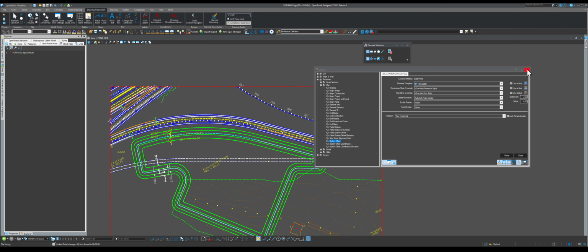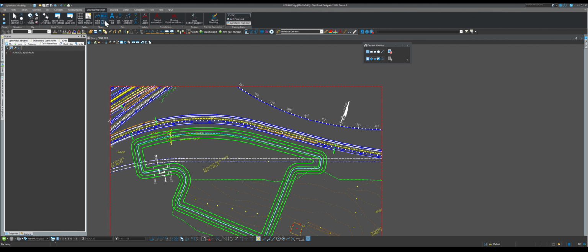We can go to the classic one here, place a label. And this is unique to FDOT because what you're going to see here might not be in your workspace. The favorite pre-saved labels are going to be different in your workspace if you're not in Florida. So I'm going to go to PL, which is plan, and then I want to find feature name. For the style, just pick whatever you want and need. Let's go with FDOT note line for now. And then let's start labeling the alignments.